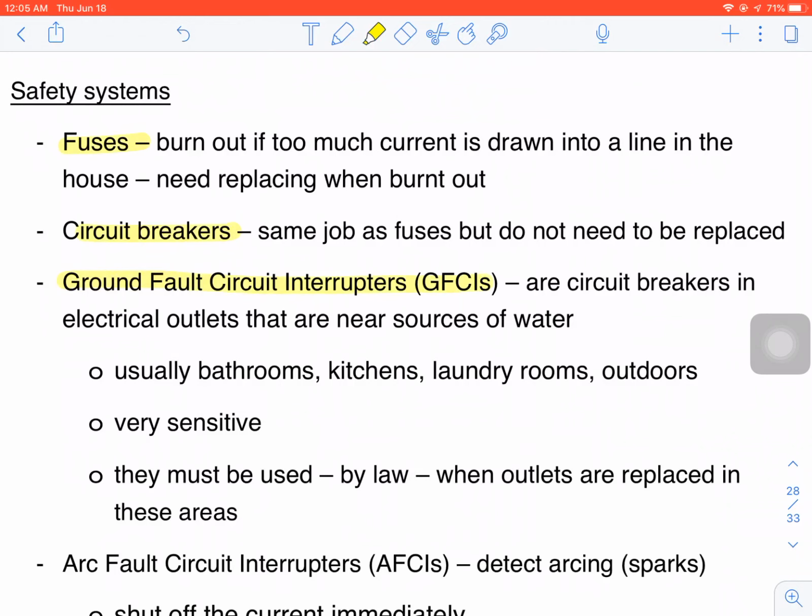Basically it shuts the electricity off, and you think, well, a fuse and a circuit breaker would do the same thing, but by the time the fuse or the circuit breaker detects there's a problem, whoever is being exposed to the electricity may be getting exposed to too much electricity. So we have GFIs in our bathroom, and the second the system recognizes that there's a short circuit, it will automatically shut off the power,